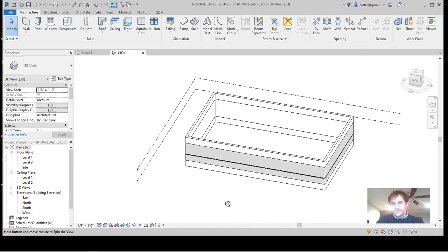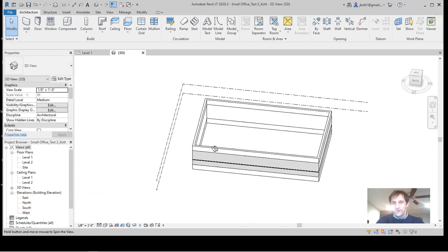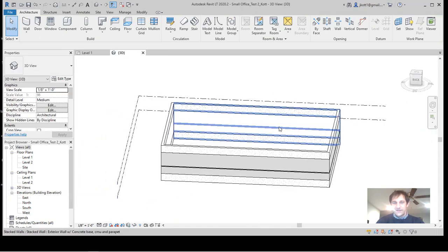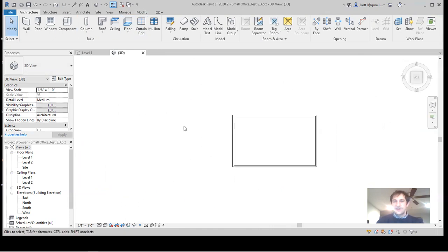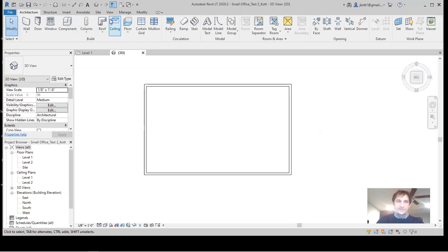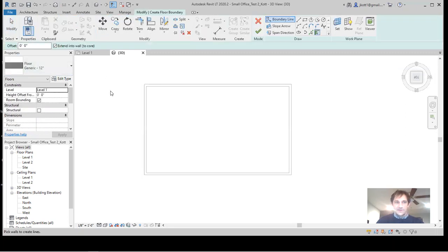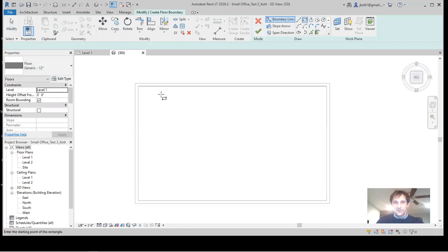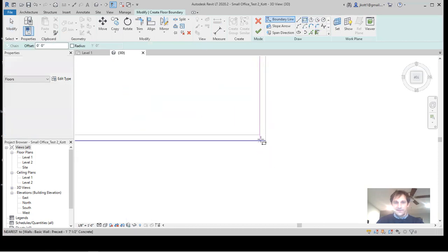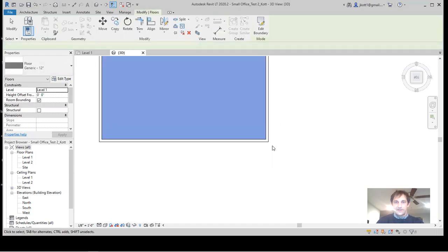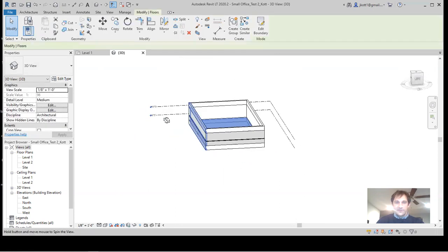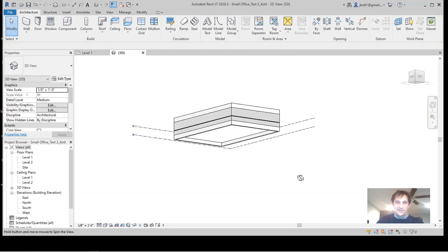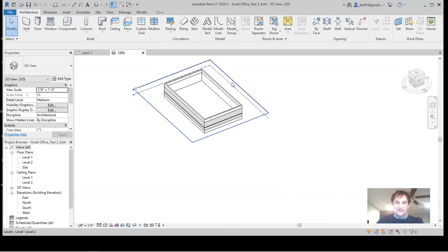It might seem difficult to understand where the floor is. Well, we haven't drawn a floor in this building yet. Because Revit LT, which is the web access version, does not offer that, I'm just going to use the floor tool instead of the massing tool. And we'll just draw our floor right on the inside of the building. I'm just using a generic floor right now. And now you can kind of see where the floor of that building is in relationship to the outside.